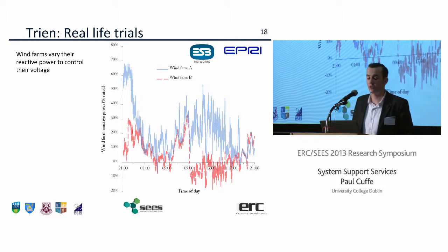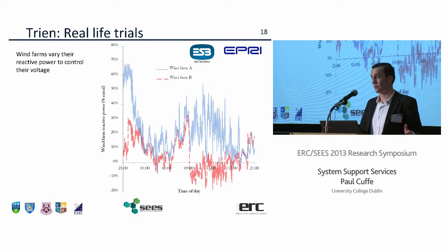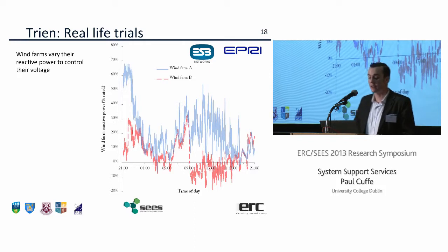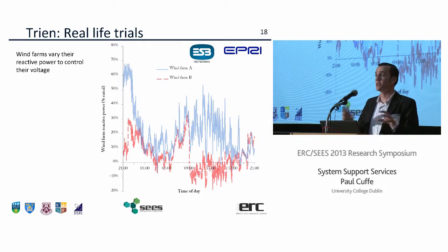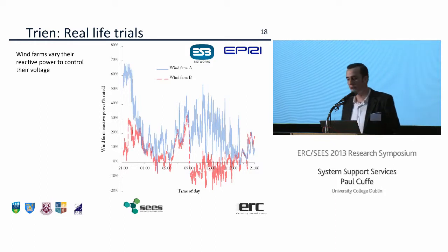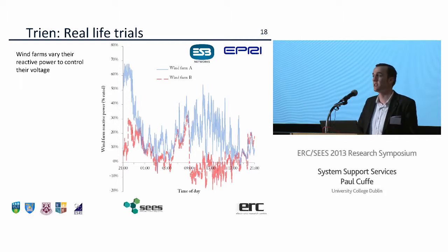We find through this trial and related work that you often don't need your tap changer so much, which is good news because you've got less wear and tear and less maintenance. You mightn't even need to specify the tap change to begin with. So there's a potential big benefit for the distribution system operator: an intelligent voltage control strategy can save them money. Because of this, it seems there's potential for some synergy here.